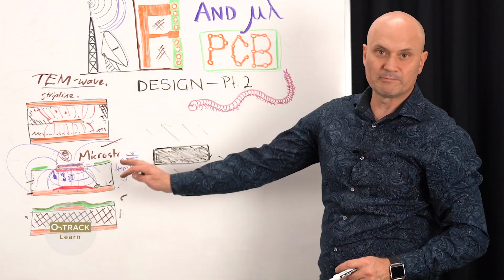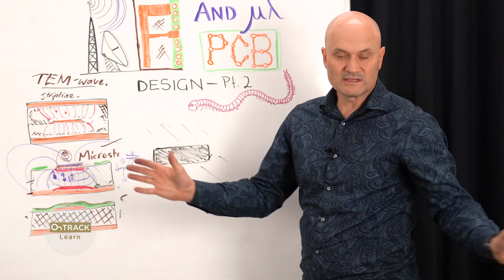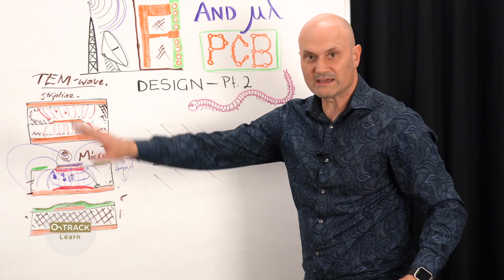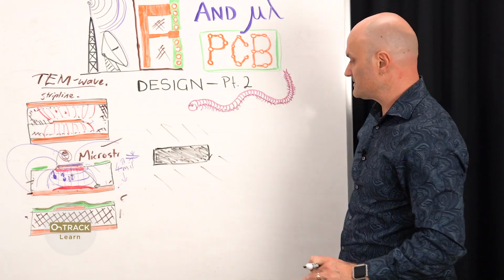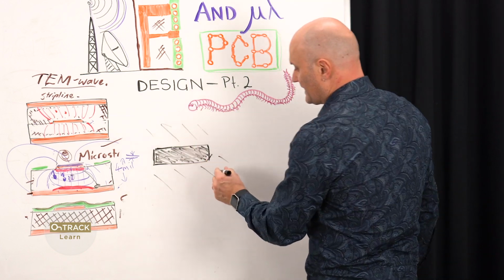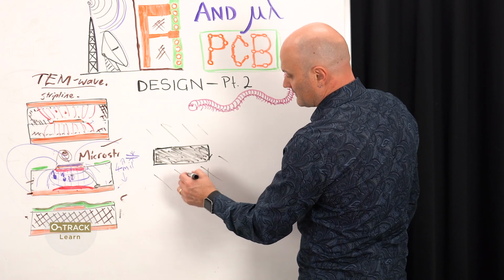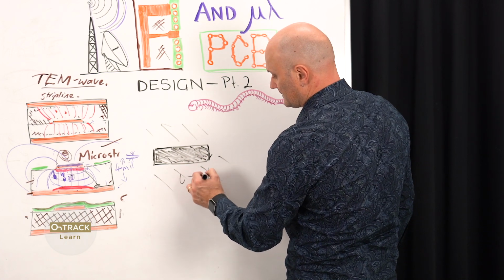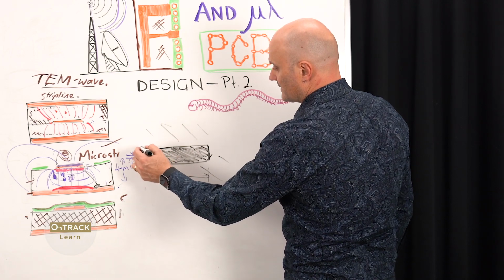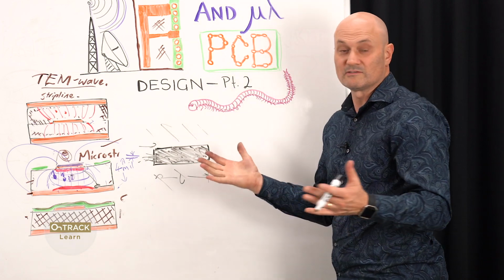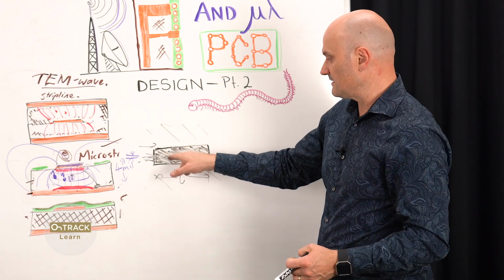The only time your copper plane is removed is when you want an antenna and you're intentionally causing these fields to radiate out. And that's another episode towards the end of this series. So we're looking down on top, and we may have a chunk of copper like this that's a certain length, L, and somewhere up here we have a pin of an IC which is a source, sending data in the form of RF energy into this trace.